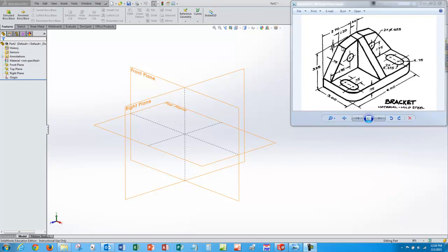I think instead what I want to do is build a view looking in from the side here. It looks like this angle. I can extrude that through, and then we'll just cut away at this little piece here, do a mirror on that extrusion cut, and then sketch on the front plane right here in the middle and sketch this little rib and extrude it to make the rib, and then come back and make the slots and the holes in these fillets. So remembering as we start our model, we want our model to orient just like it is in the drawing here on our screen when we get our ISO view.